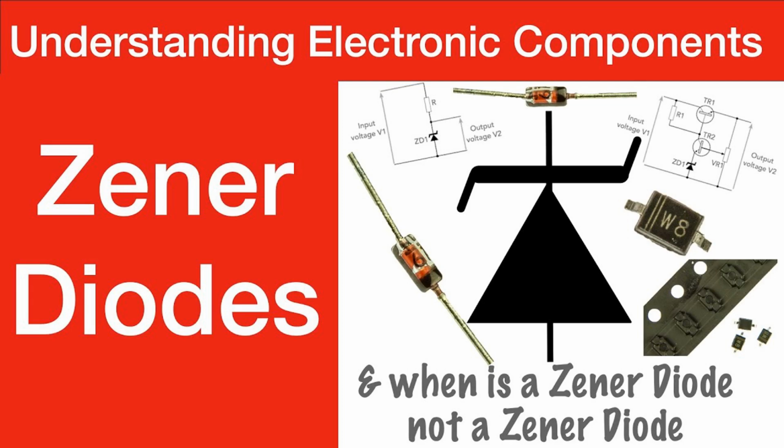2. Reverse current, or breakdown current. When the reverse voltage applied to the Zener diode reaches the Zener voltage, the diode conducts a significant current in the reverse direction, known as the Zener current, IZ. Minimum current is the minimum current required to maintain the Zener voltage.